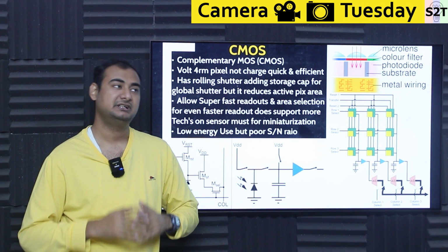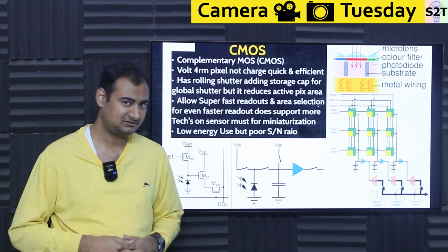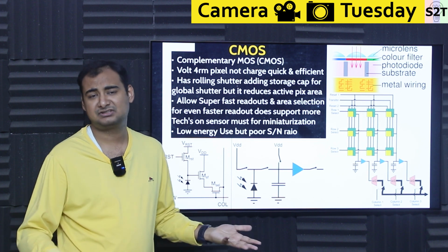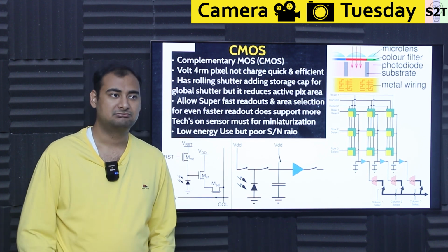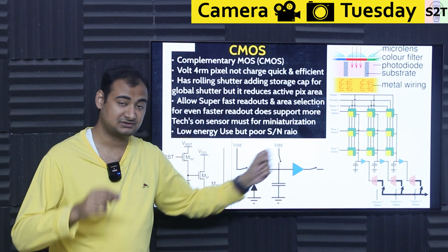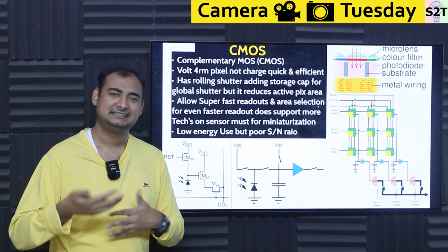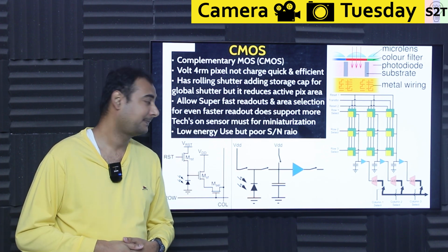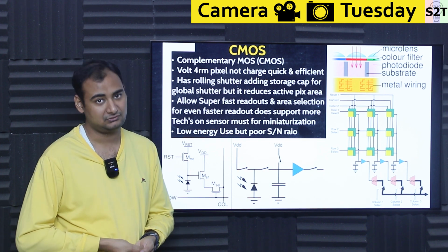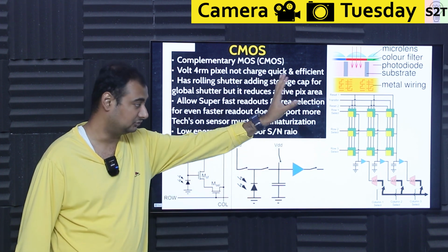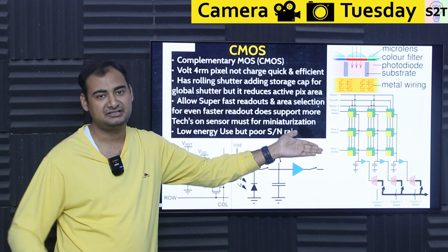You choose rolling shutter, it will give you at best 16 stops of dynamic range. Now for most scenarios, people prefer a better signal to noise ratio. Be mindful, pixels will be physically larger, so they're like, hey, I can deal with rolling shutter. So that's why we are stuck with rolling shutter. We know how to make global shutters, we just don't, because it fundamentally reduces your quality.